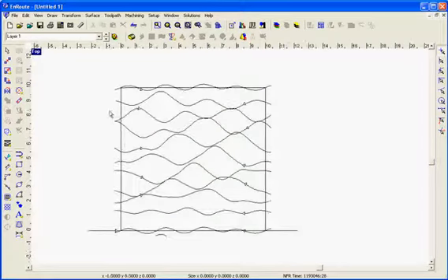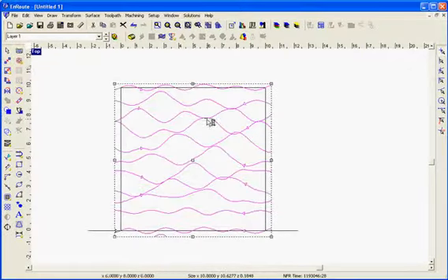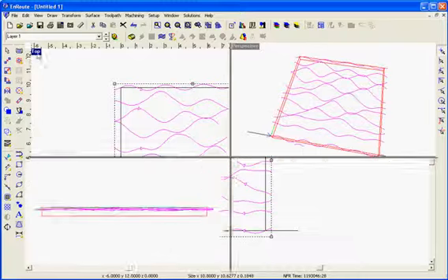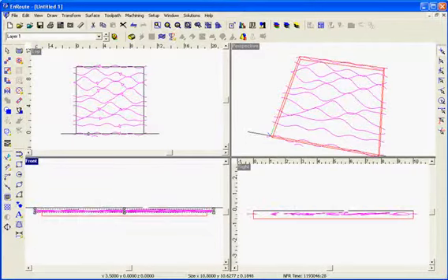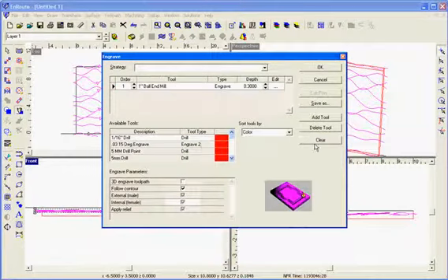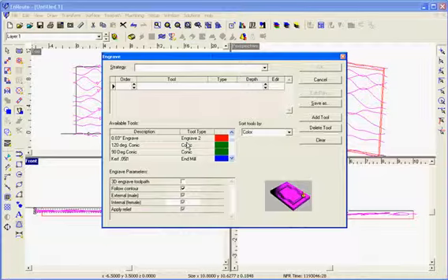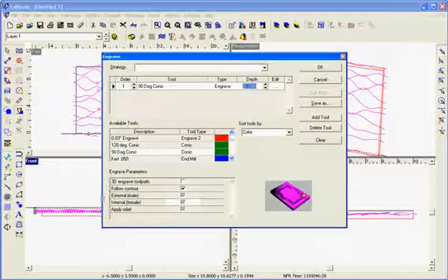And this shows us what our part's going to look like. I can come here and move this into my plate a little bit. That will help to create a little deeper effect. And for this particular rapid texture, I'm going to use a 90-degree conic tool. Because I have follow contour checked, the depth is not going to be followed because we're going to follow the lines to create the tool paths.